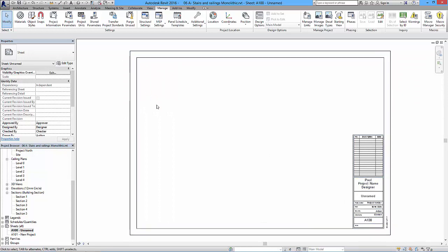And then depending on which type of printer you use, you're going to be chopping into the edge really, because this is the sort of size of the paper, and then you'll end up with a boundary depending on how good your printer plotter is. It's going to crop it. What we don't want to do is print this off and fit to scale, because then we're not going to scale the objects correctly in the viewport. So to do that,